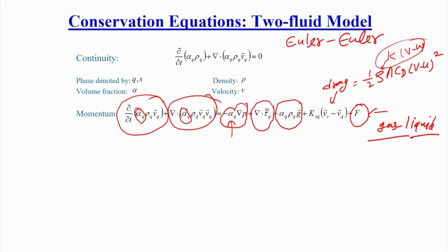Now, once the flow is solid, things become a little bit different. When both the phases are fluid, things are a little bit simpler. You solve exactly this equation, a pure Navier-Stokes equation, or very close to the Navier-Stokes equation, where you just include a drag force, which is the interaction between the two phases. You just multiply with the volume fraction of each phase in that place. Each term is multiplied by the volume fraction, so that if you sum both the equations, you will get the total forces acting within the whole domain. That is the way it is solved.